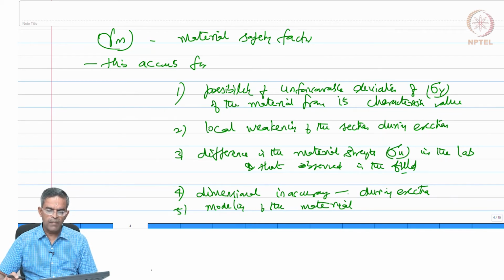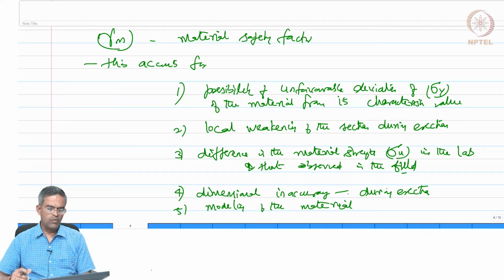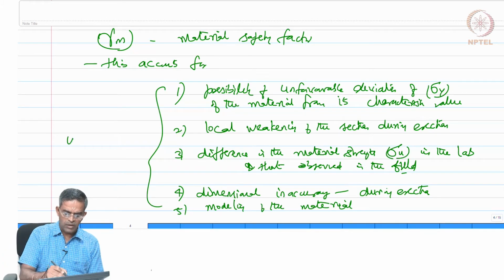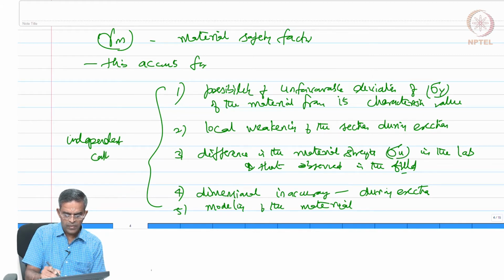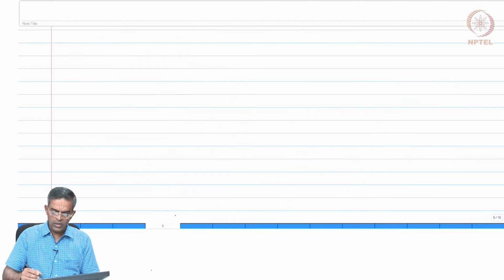So for example, if gamma f is 1.5 and gamma m is 1.15 as in Indian codes, you will not come to know this 1.5 will be a contribution from various sources, or what is the effect of every factor on this gamma m. You will not know these independent contributions, but they are together contributing to gamma m. We can only know that.